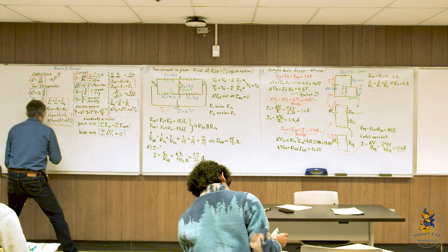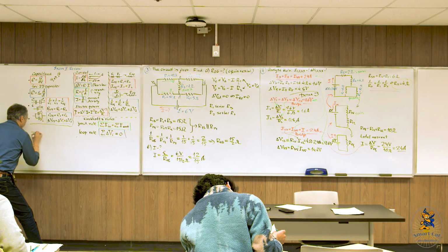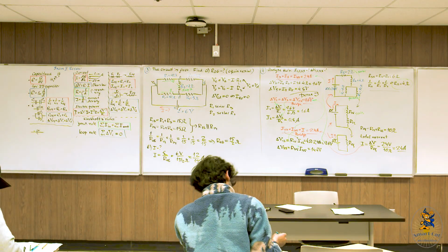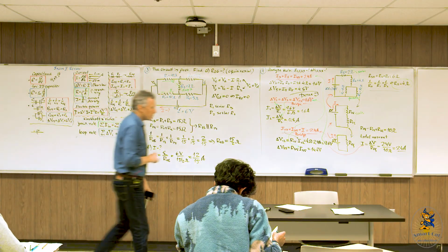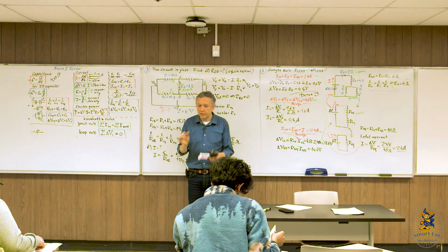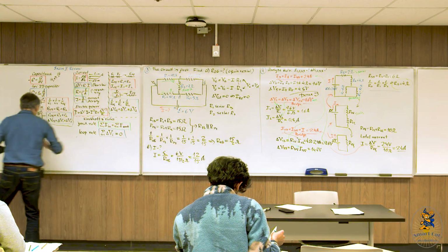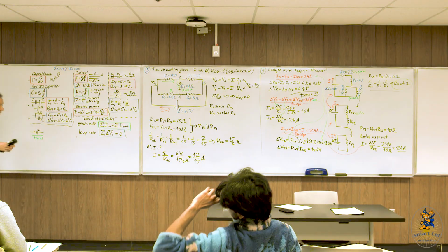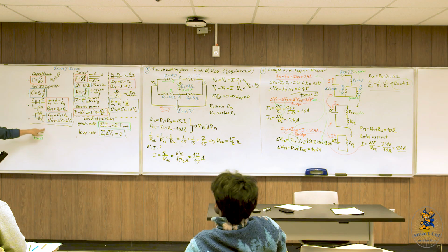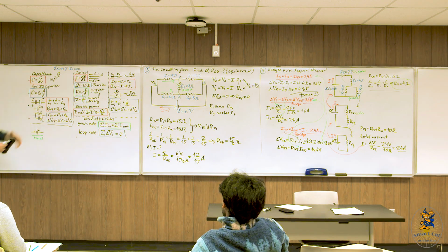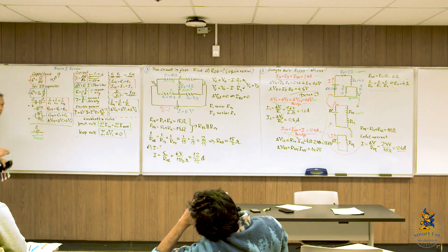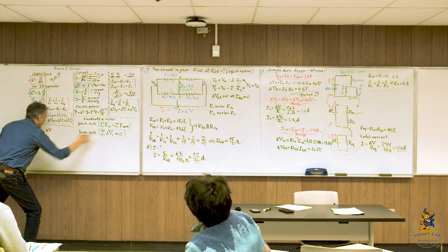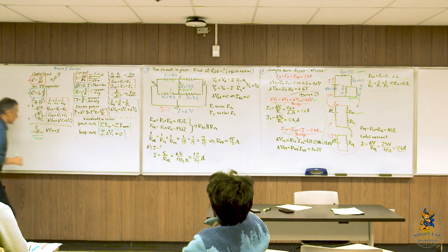So, if we have a battery, let's say like this, so it's a plus and minus, and you remember every time when you apply the loop rule, you need to pick a travel direction. So let's assume that in this case, travel direction is this way. So if you travel from minus to plus, electric potential goes up. And if the EMF of the battery is given, the potential difference delta V contribution to this loop equation will be plus EMF. So it's rule number 1.